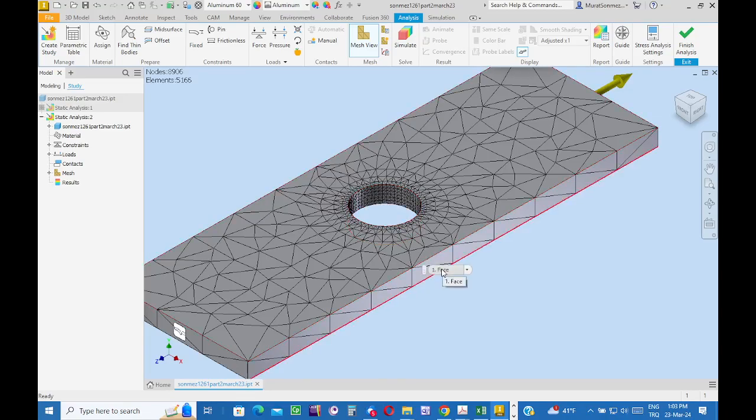If you indicate the edge, that is going to be wrong because the feature extends from here to there. It is a whole. In the vicinity of the edge, Inventor uses a finer mesh, not the rest. Here, if it is a surface, and in the vicinity of the surface you need to find the solution more accurately, indicate the surface, not the edge. I indicated the surface. I brought the cursor not here, not there, but to the surface, and indicated.